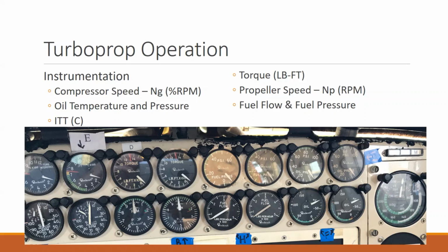You may actually overspeed it before the prop governor or the overspeed governor or the power turbine governor is able to take that into account. Okay, these are mechanical systems with feedback. They take some time to react. So you want to make sure that you're paying attention so you don't damage anything in the process.